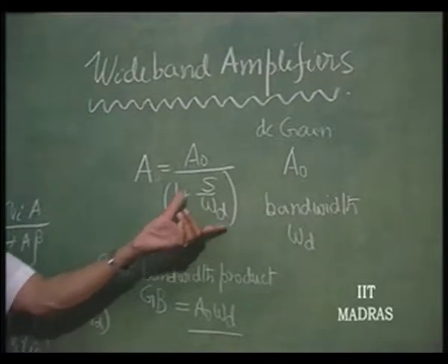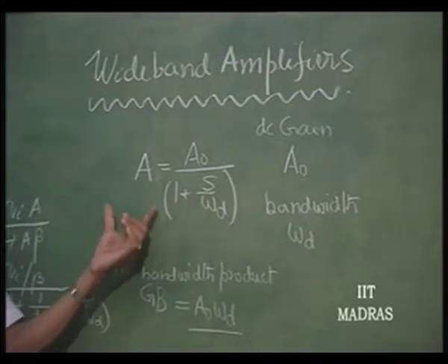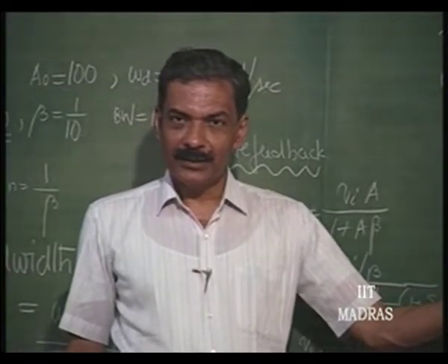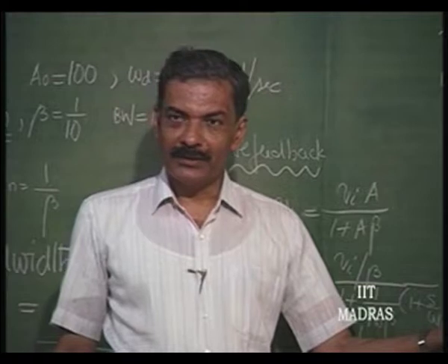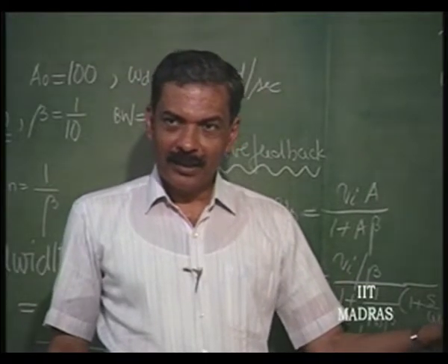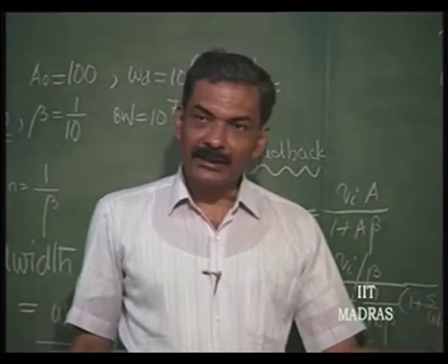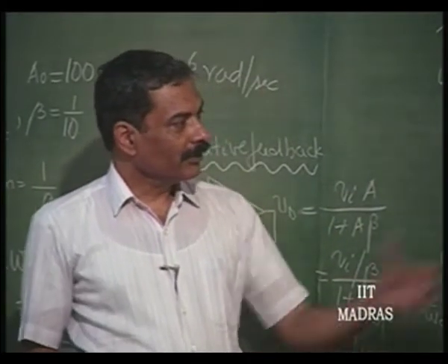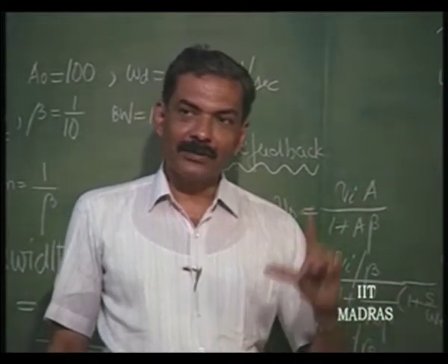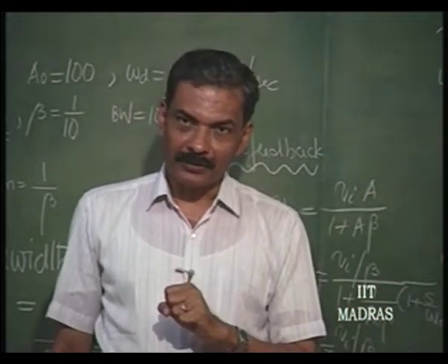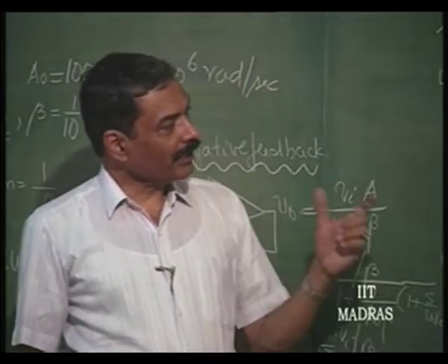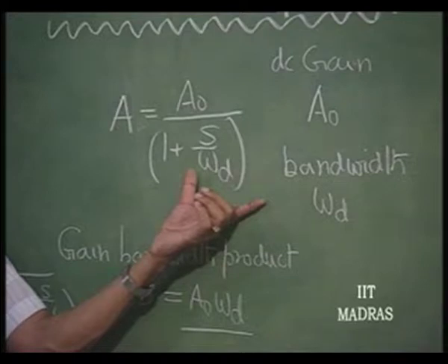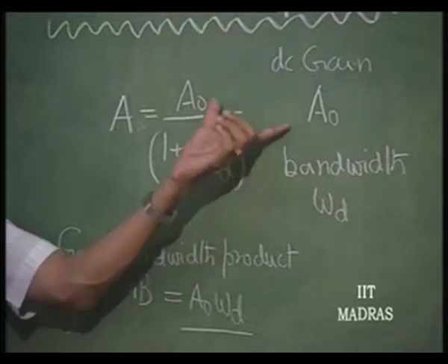So, even after cutting down the bandwidth, the gain into bandwidth is going to remain constant, and within that gain bandwidth product you can get wideband amplifiers designed with desensitized gains, etc. But this kind of dominant pole compensation is always going to result in a lower gain bandwidth product. Instead, I said we can convert that third order system into a second order system by using pole zero compensation.